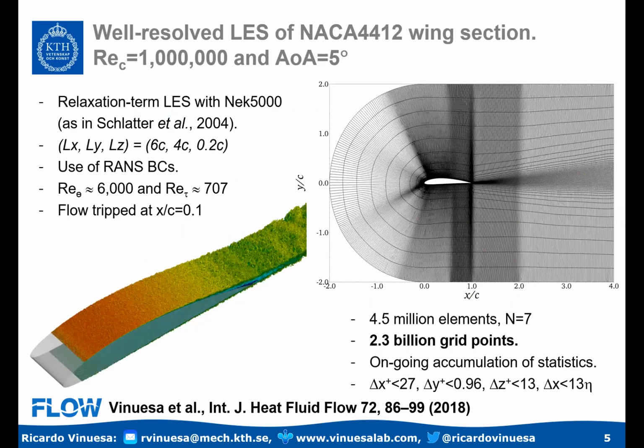Now, the turbulent wings that are infinite, these span-wise periodic cases, can give us some information about pressure gradients, turbulence, things like that. But there is one limitation when we come into the meshing. As you can see here, the elements in the far field are very elongated because this is a conformal mesh, and that has quite some limitations in terms of the pressure iterations that we have to do in order to integrate the governing equations.